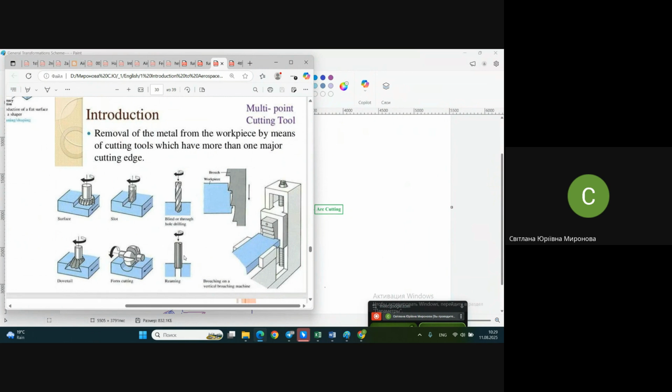On one hand, it seems more convenient to do something faster with single point or multi-point like milling. But on the other hand, if you'd like higher quality, you need to use abrasive tooling. How this problem is solved, you already understand: by combination. First, we remove some layers with quick techniques, next we continue with a multi-blade tool, and finally it's maybe finished with an abrasive tool.